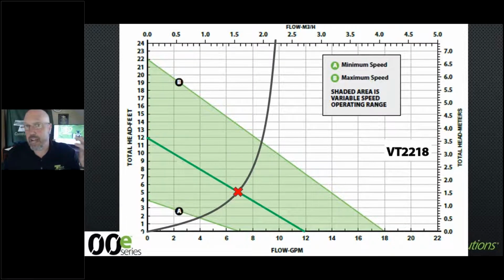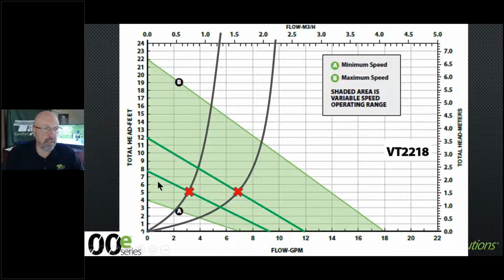And then if you had zones in here and a zone valve closes, it would bring down to that 3 gallons a minute, 5 foot head. So it's always going to operate, say, in between these two curves. You know, your middle curve, that's our maximum, and then there's our minimum. On startup, when everything's nice and cold, we might see it ramp up a little bit higher in order to maintain a fixed delta T. We could see some ranges that could go up and down on here.